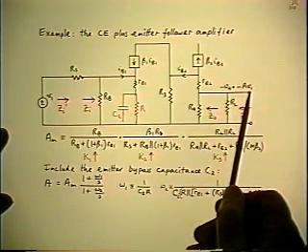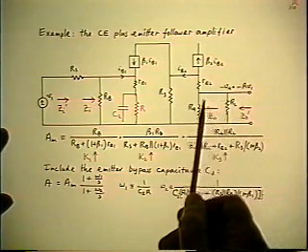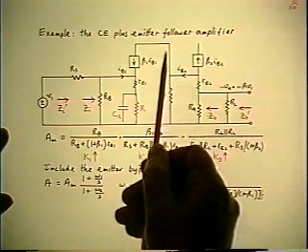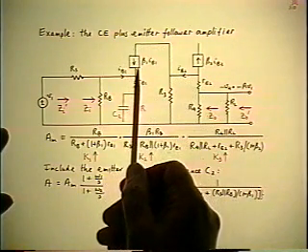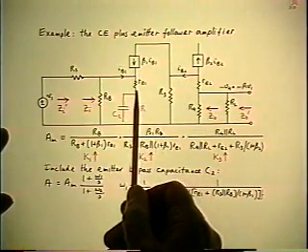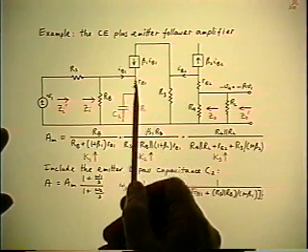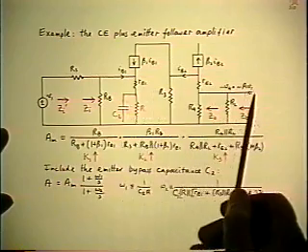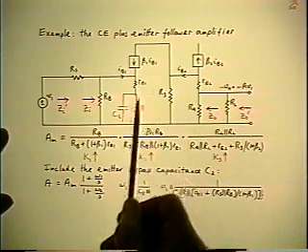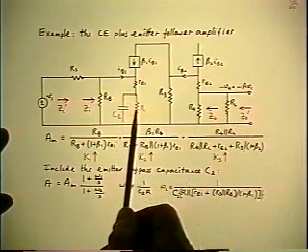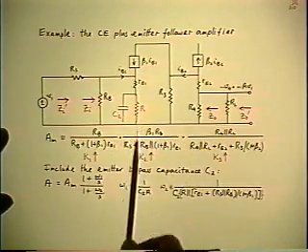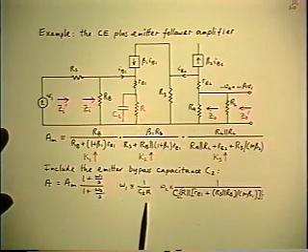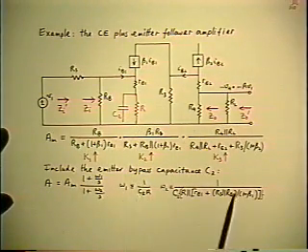If you propagate the null backwards, everything has to be null all the way back to the collector of this transistor and therefore the emitter as well. Once again you end up with the requirement that the emitter current is 0 if the output is null. Therefore the impedance seen looking in is just R. So the Rn is R, and that identifies the zero.